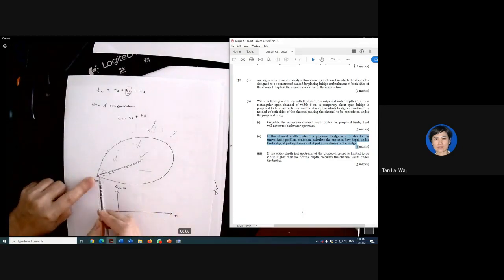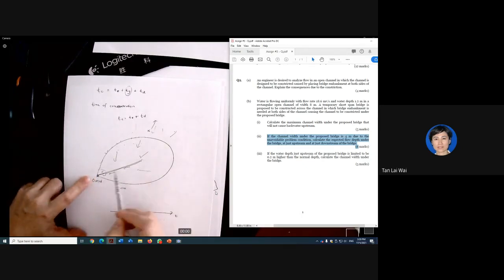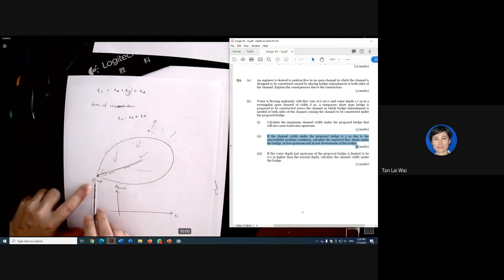So which part would have the maximum Q? The most downstream part. It will get Q max. So therefore the size of the drain, of course, you want to make it standard size. You are going to get the maximum based on the Q max. If you order different sizes of drain, the supplier will be having a hard time to comply with your demand. So just order standard size. All right, so looking at this Q outlet here.